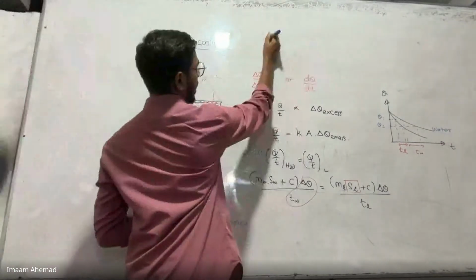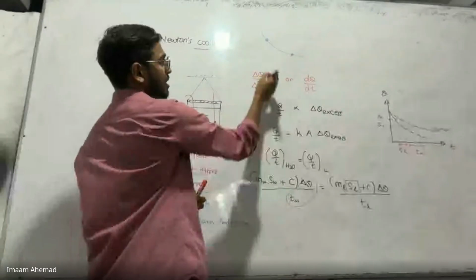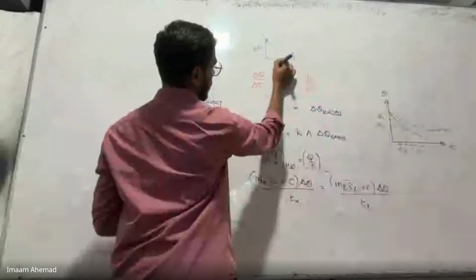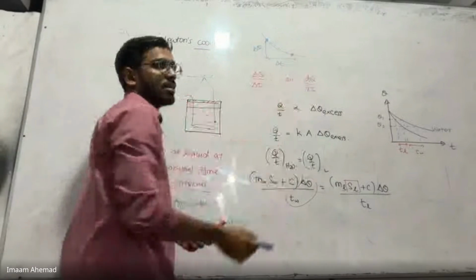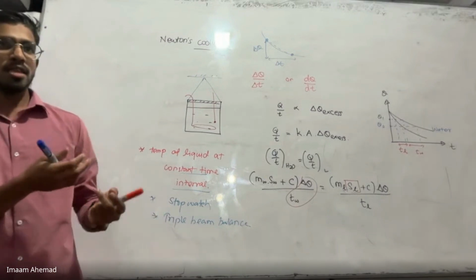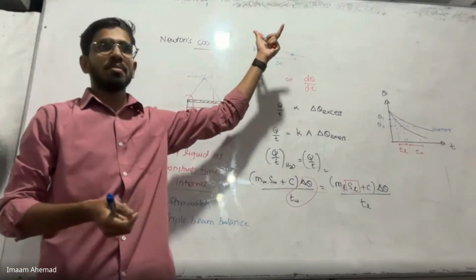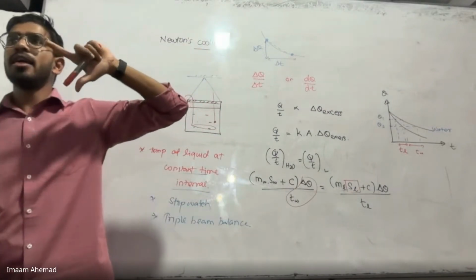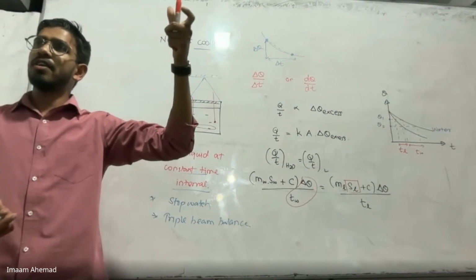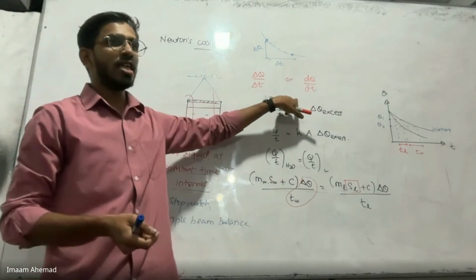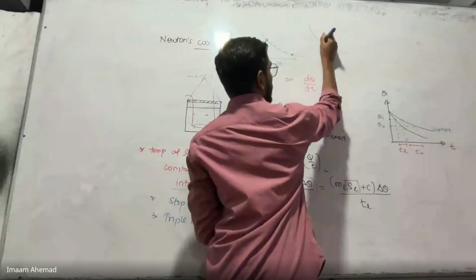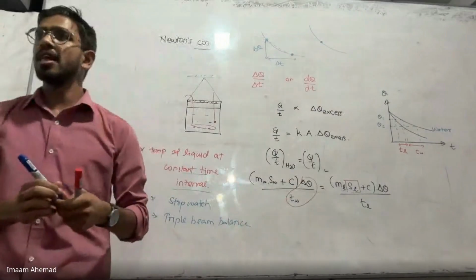In that, you take any 2 points and get this difference, delta theta, over this difference, delta t, by constructing a right angle triangle. So if we do this, this is delta theta over delta t. You get the gradient. Here, you are getting the average cooling rate. You are getting the average. What is d theta over dt? We get the same thing at a single point.